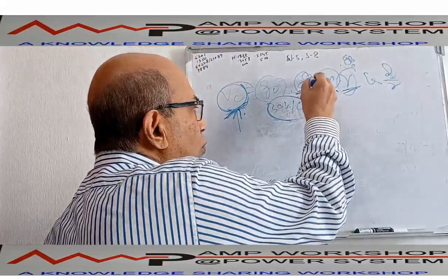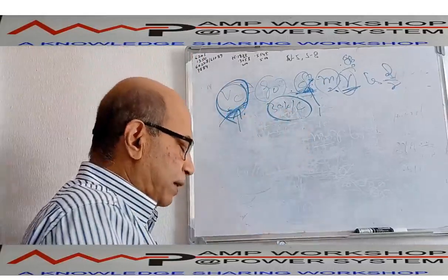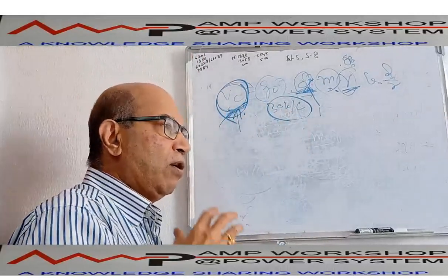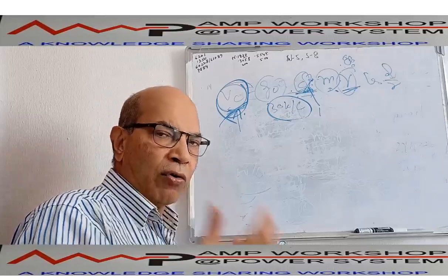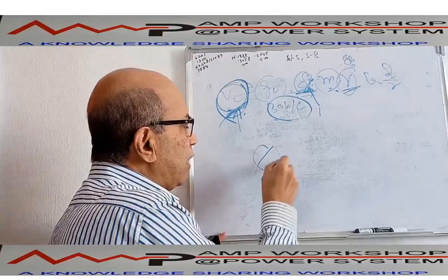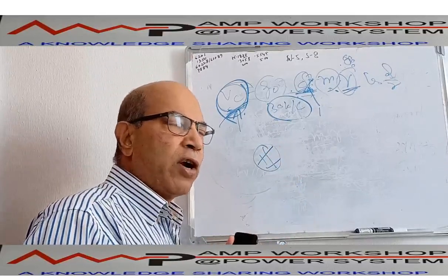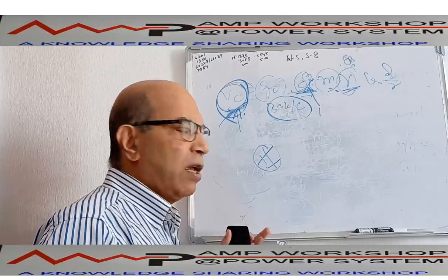If it is more than 1, then immediately disruptive breakdown takes place, because this value will be more than 30 kV per centimeter. So that's why, when you want to reduce the corona, one way is to reduce the conductor radius, so the conductor has a smaller diameter. So in the case of high voltage transmission, 220 kV or 400 kV or 800 kV or 1000 kV transmission,